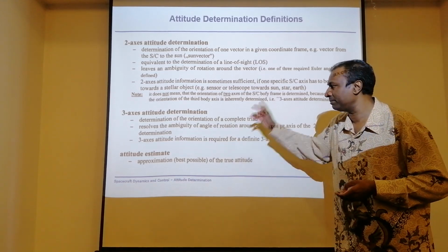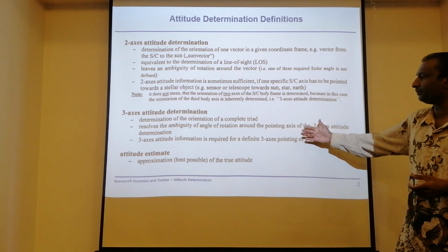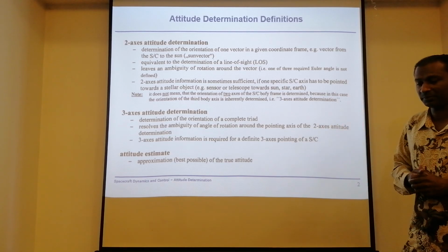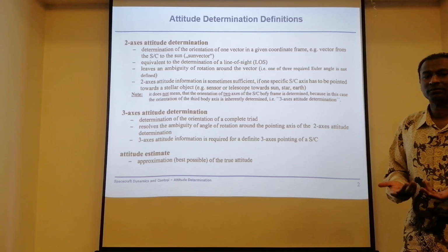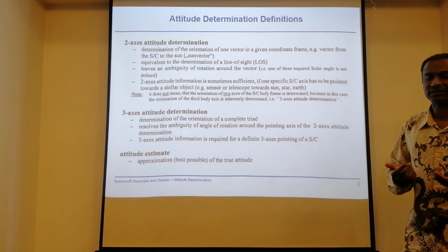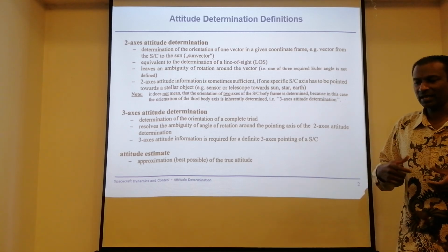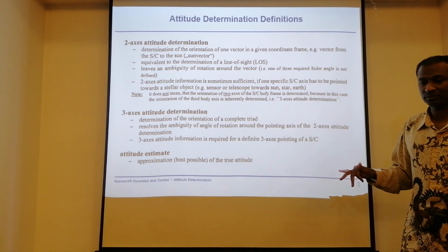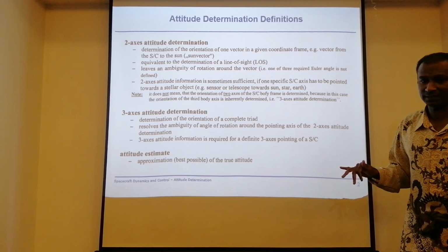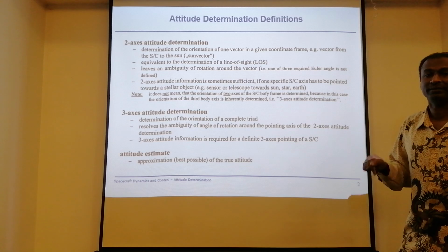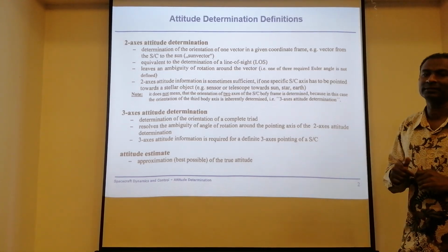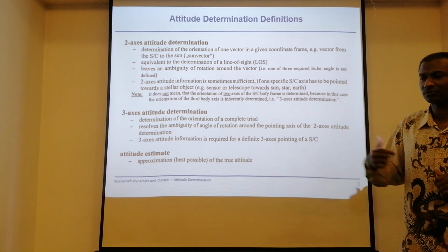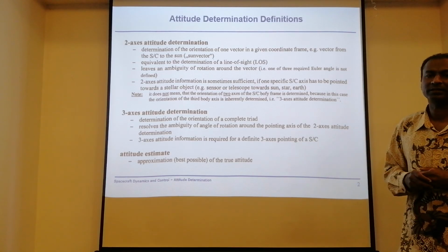So for 3-axis attitude determination, I can have a sun sensor, for example, and I can also have a gyro added for the yaw axis. When I have a sun sensor along the Z axis, I should be able to take care of the roll and pitch motion, or sense the motion. I assume that both of them are basically coupled in any case. So I can have that motion detected via my sun sensor, and for my Z, which is the yaw, the rotation of that axis, I can simply have a gyro to give me that motion.